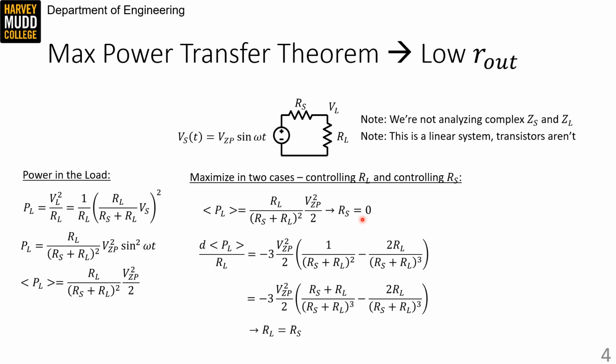One final note, efficiency is a very fundamental measure of power transfer. It's the ratio of power delivered to the load divided by power pulled from the source. And you might wonder what the maximum efficiency of a matched power delivery network looks like. The answer is pretty bad, because RS is equal to RL when we have maximum power transfer. We know that the voltage to the load is half the source voltage. Squaring that gives us a peak efficiency of 1/4.